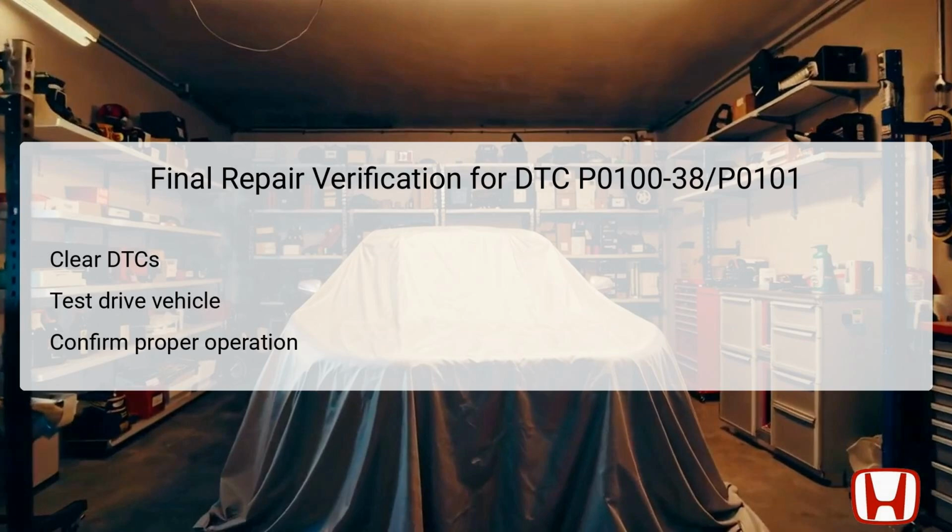After completing the necessary repairs, it is essential to verify that the issues related to DTC P0100-38 and P0101 have been resolved. Start by clearing the diagnostic trouble codes using the Honda Diagnostic System, HDS. Once cleared, take the vehicle on a test drive, ensuring to operate under varied engine loads and speeds to confirm proper operation. Pay attention to the performance of the engine, looking for any symptoms that may indicate lingering issues.